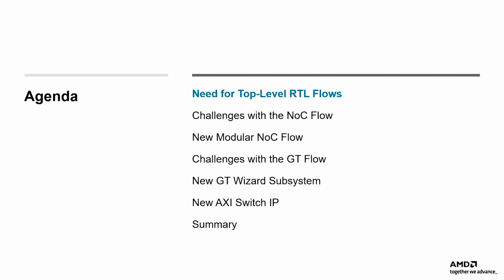Today, customers designing with the Versal Adaptive SoC have to use the Vivado IP integrator to configure key components like the SIPs, NoC, and gigabit transceivers. However, most users are still more comfortable with RTL development. These users face challenges with the IPI-based flow as it doesn't offer the same level of control and flexibility as RTL coding. To address these challenges, AMD is introducing an RTL-centric flow in Vivado 2024.2.